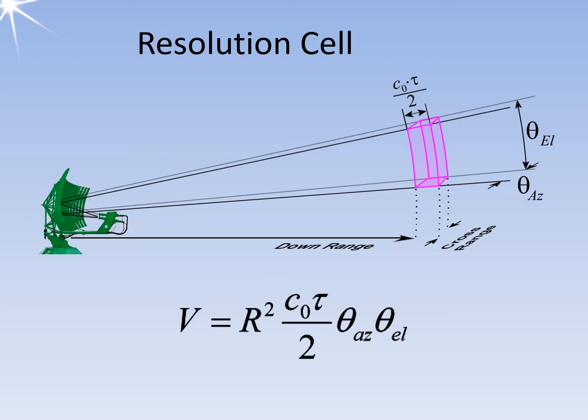In weather radar, the resolution cell has greater significance. Since the volume of the resolution cell increases with increasing distance, many more raindrops will now fit into it for the same rain intensity. The radar cross-section will thus also increase. This increase affects the maximum range of a weather radar. Because of this, reflecting objects in weather radar are also referred to as a volume target. The volume target fills the resolution cell. In contrast, surveillance radars usually detect point targets. The reflecting object gets lost in the increasing volume with increasing distance.